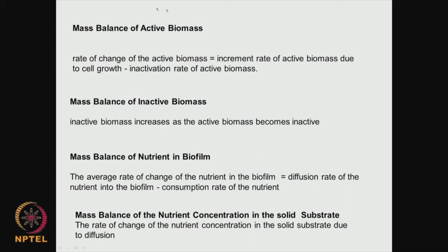Okay. So, with all these terms, we can have differential equations, it can be non-linear differential equations, because when you talk about the Monod equation, you can have a non-linear Monod term here. Okay. Then we can have the fraction of the active biomass going into the inactive form, and then for the mass balance of nutrient in the solid, we can put in something like a Fick's law term here. So, all these equations can be put together and they can be solved. So, we can get a